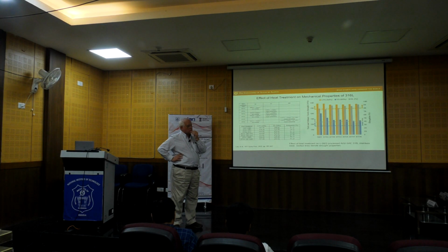There was some work done by Tom Starr at the University of Kentucky years ago, where he was doing directed fusion of metals. He found that for certain metal systems, namely the ones with really high toughness, finishing the surface had no effect, because the internal defect structure was driving the fracture, not the surface effects.